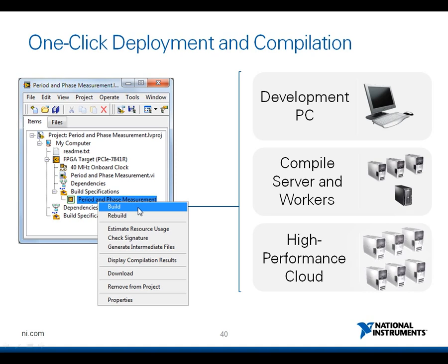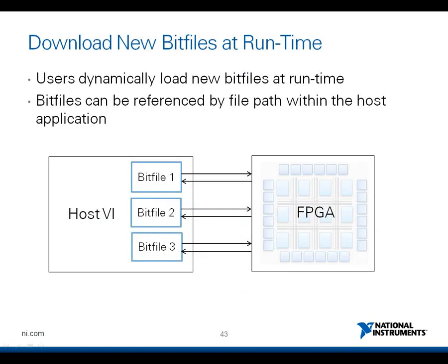As FPGAs are reconfigurable, from your host VI you can load multiple bit files to the FPGA during runtime. You can reference this bit file by a file path from within the host application. In this way, it enables your application to run in multitasking modes.